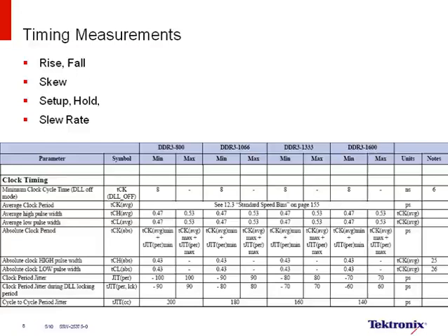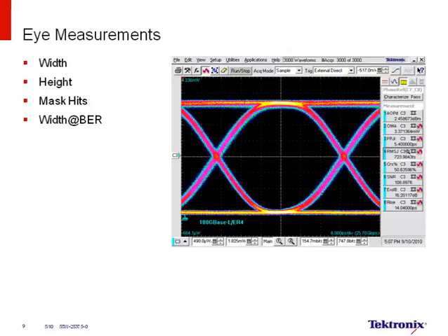In the world of signal integrity, we make lots of different measurements like high time, fall time, rise time, peak-to-peak jitter, setup, and hold. The eye diagram combines a whole bunch of different signal integrity measurements and jitter measurements like rise, fall, peak-to-peak, period, setup, and hold into a simple picture. Sometimes you also see an eye diagram with a keep-out region or a mask. The key to performing and understanding these measurements is to understand how the eye is created.